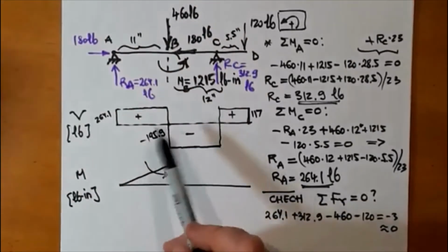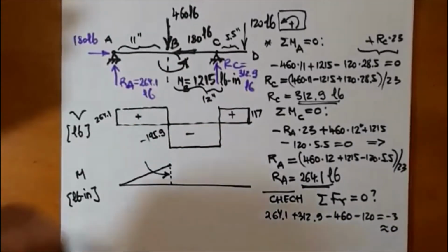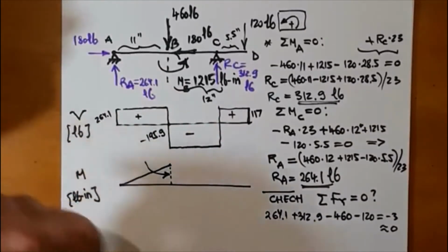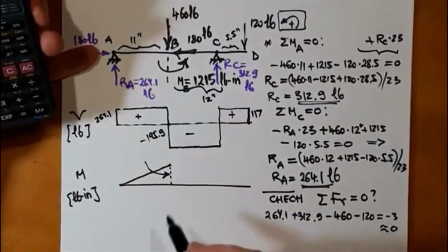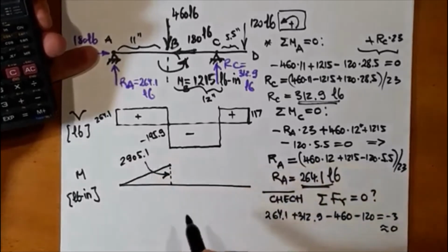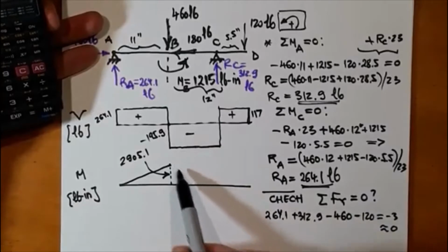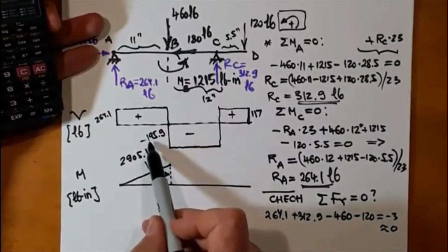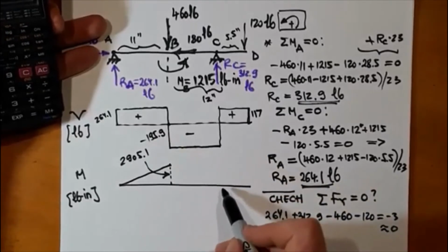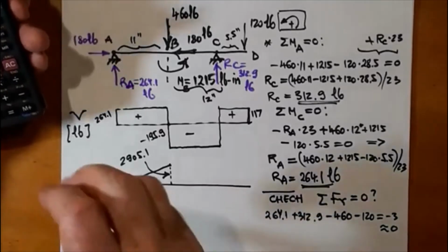It is going to be the area principle, so the area of this rectangle, 264.1 times 11, is 2,905.1. So 2,905.1. The slope changes, and it's going to go negative 195.9, and I'll have another minimum. So let's see what the balance of moments is.